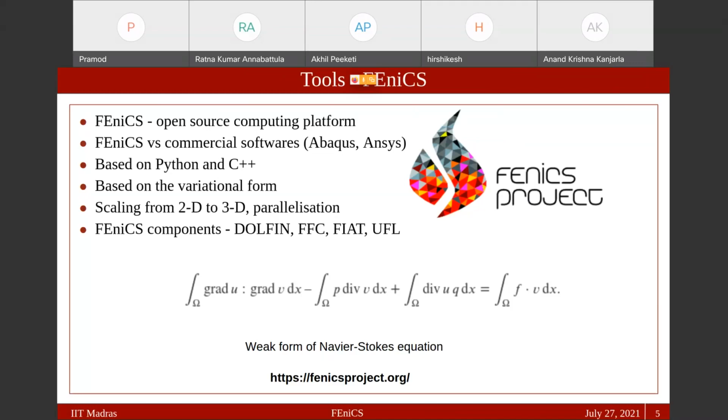And the second part of the question was how it is different from MATLAB. In MATLAB, the way I have coded, at least as far as the linear problem goes, if the domain is too big and the number of elements is too high, the most expensive part is usually assembling the global stiffness matrix and then solving it. So those parts in MATLAB can be very expensive. Secondly, in MATLAB, you have to start from scratch. I mean, you have to load the domain.